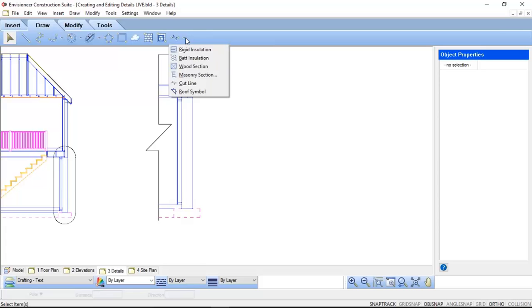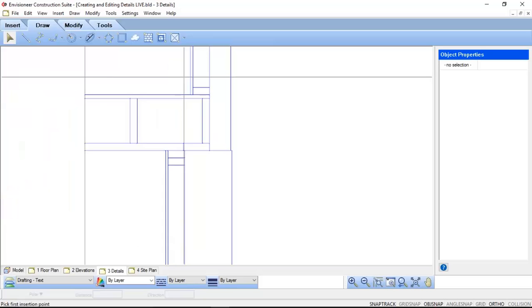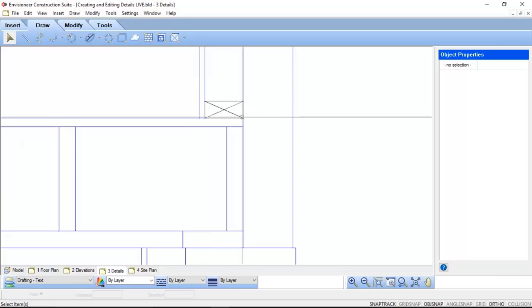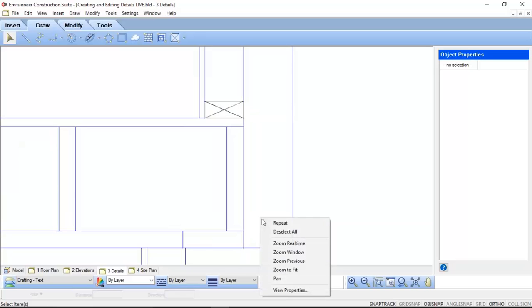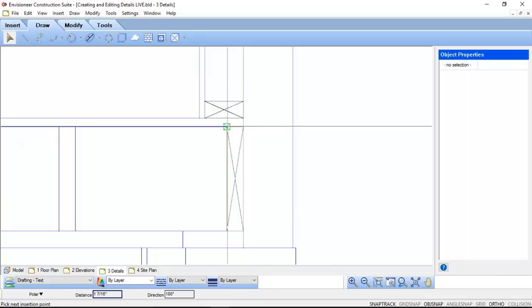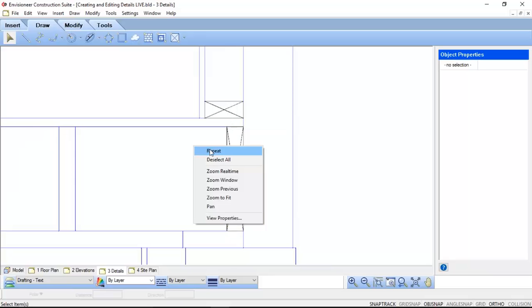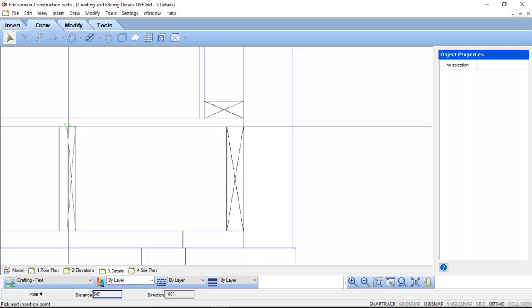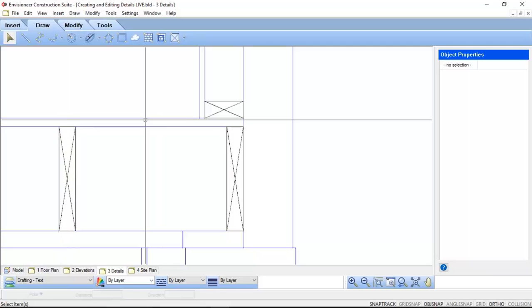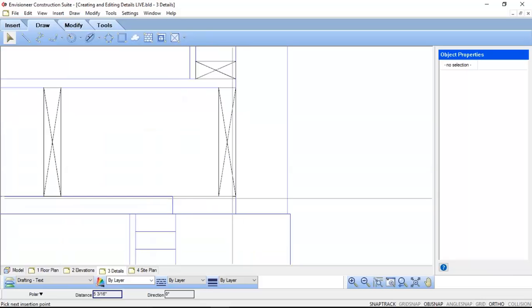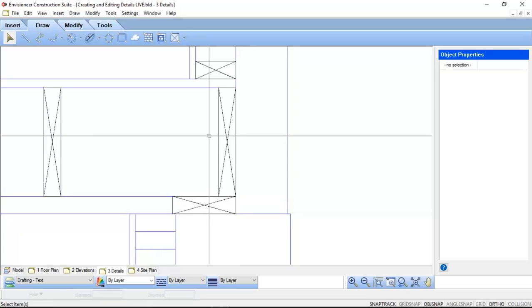One of the other things I can quickly and easily do here is add some wood section marks. So I'm going to come in anywhere that I'm cutting through wood members, like that sill plate there. I'm going to do my floor joist members. And to work this tool, you simply click on one corner, drag straight up or straight across, and then extend to get out to the other edge. So it's 3 clicks. Do that again here for this other sill plate sitting on top of our stem wall.